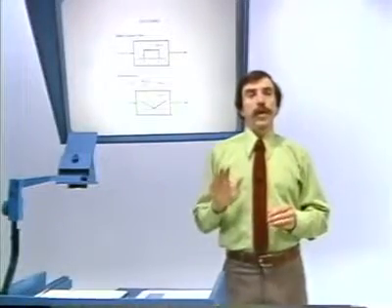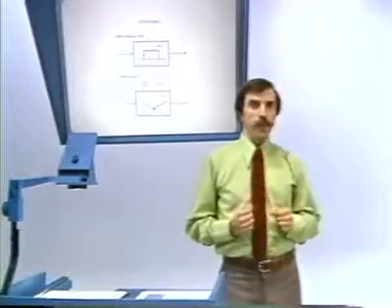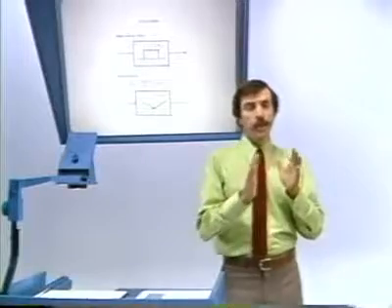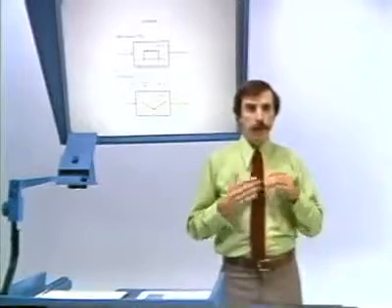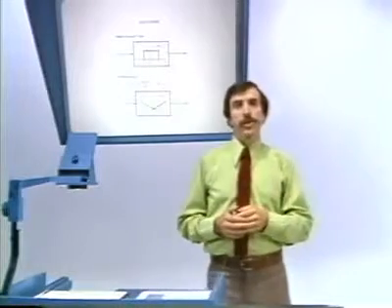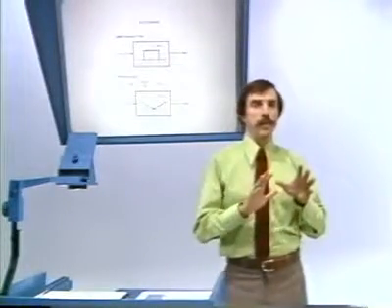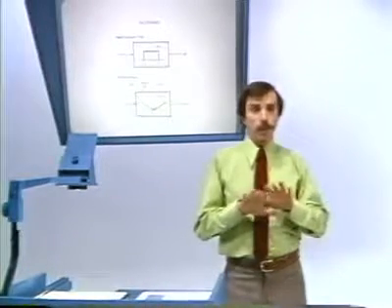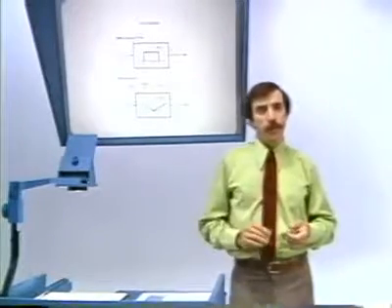When we talked about square waves and saw how the Fourier series built up a square wave, we saw that it was the high frequencies that were required in order to build up the sharp edges. And so either viewed as a filter or viewed intuitively, we would expect that the differentiated image would attenuate the slowly varying background and amplify the rapidly varying edges.